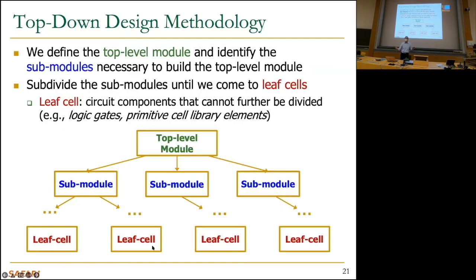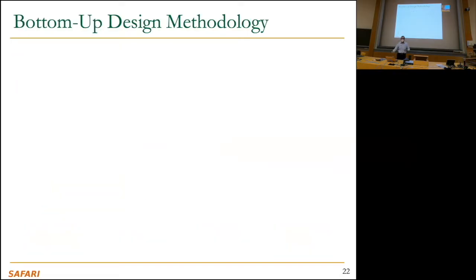Does that make sense? Okay. So basically, your hardware description eventually ends at these leaf cells. But remember that leaf cells can be at different levels of abstraction also, if the library provides that abstraction. In fact, it's very nice to have that abstraction. Somebody designed this beautiful multiplexer, 8-to-1 multiplexer. I don't care how it's implemented. That's my leaf cell. If I'm going to use that in a submodule, I'm going to just instantiate that leaf cell. I'm not going to go into the AND or NOT gates that implement that leaf cell. Okay, that again tames complexity.